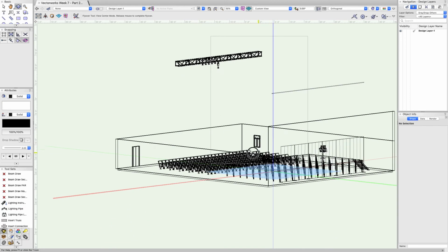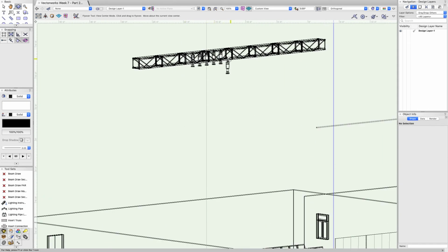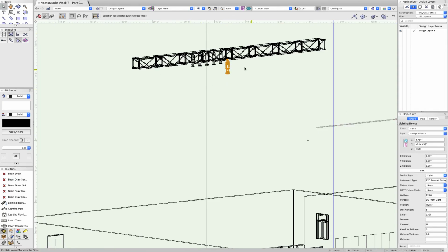And actually, I'm noticing that these ones clamp to the top of the truss. This one's actually down where I want it to be. So the way I'm going to adjust this, I'm going to hit this light and see where its Z-axis is, 35. And I can highlight these ones that didn't go to the right point and just adjust their z-axis down, and they'll automatically clamp to that cord of truss rather than the top.